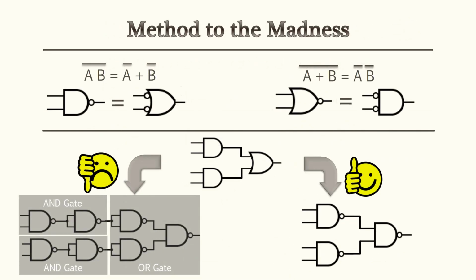You're probably wondering why I stressed not to use those tables on the previous slide. Well, I created a circuit here using those equivalencies from the previous slides on the circuit at your bottom left. There are 7 NAND gates. That's 4 excessive gates needed to create the circuit you see on your right. And all I did was use those equivalencies from the previous slides.